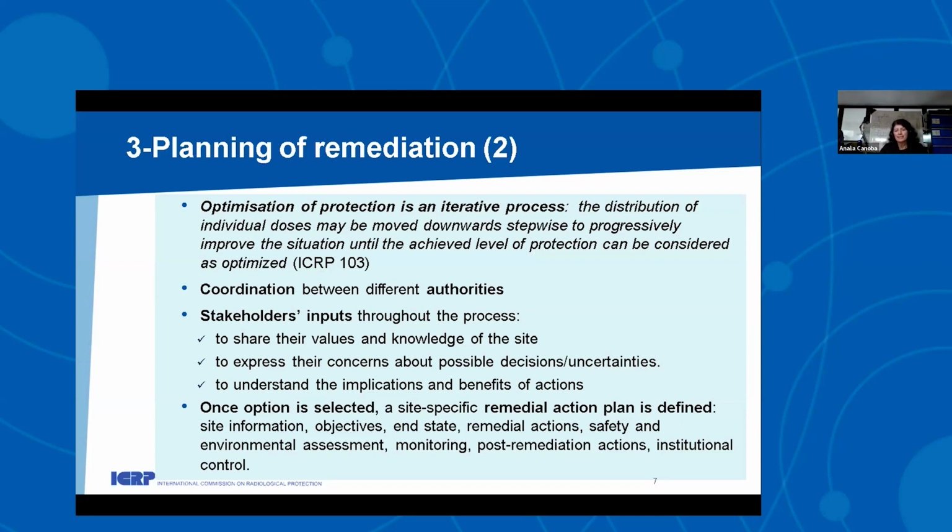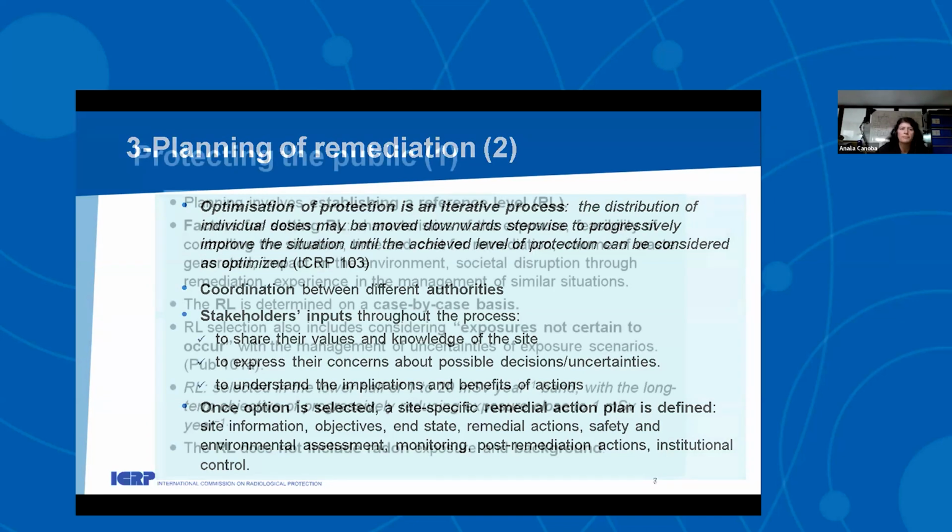Once the option is selected, a site-specific action plan should be defined that should have all the information of the site: which are the objectives of the planning of remediation, which is the reference level, the end states, the remedial actions, the safety and environmental assessment performed, which are the monitorings that have to be performed, and also the post-remediation actions, including the institutional control if decided and needed.